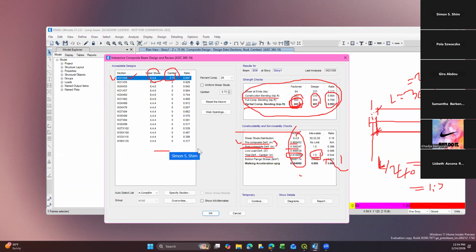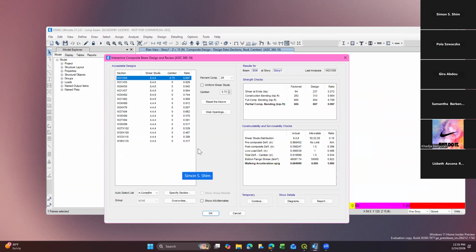Okay, if using the same depth girder, the same beam here, you need to cope it. So let's say you need to cope this top and bottom, right? So both connections, same depth, you need the top cope and bottom cope. So in some industry, we're using a little bit deeper girder. We maybe choose 24 by 55, if the architect doesn't have any headroom issue.